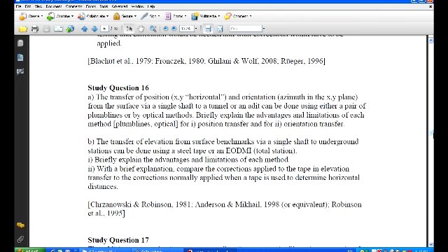When we compare the use of a tape vertically to horizontally, we have with horizontal tape, calibration, temperature, sag, and stretch. The sag isn't there anymore because the tape is vertical. The stretch is a more complicated formula, although there is a separate one to deal with the fact that the tape itself is exerting tension, but there's also the one for the tension different from the tension at the time of calibration.